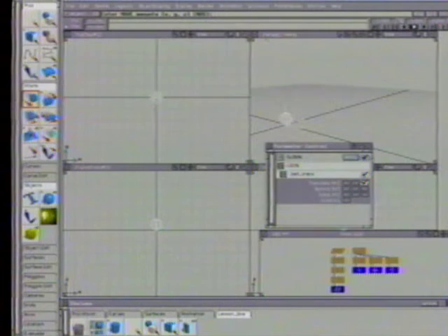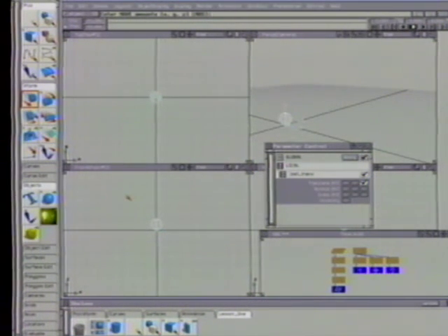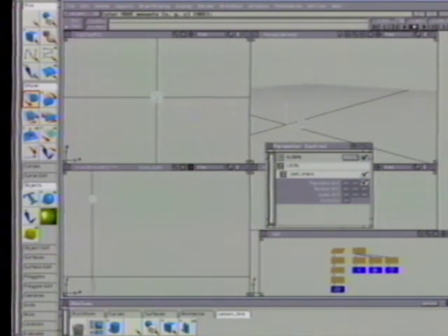In the time slider, go to frame 0. Go to the X-form section of the Tool palette and select Move. Enter 0, 0, and 10 to move the Ball Trans up 10 units. This is where the ball will begin to bounce. Dolly and track in the front window until you can see the ball and the ground. Go to the Animation menu and select Set Keyframe.